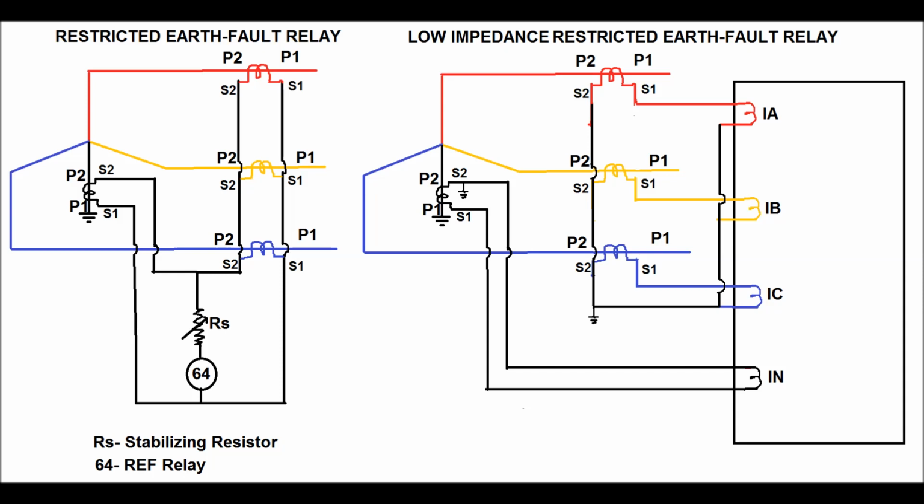But in case of the secondary connection of the NCT, the two terminals are taken to another coil of the relay, called the sensitive coil or earth coil of the REF relay, that is the numerical type. Again, the CT polarity connection in the relay should be proper.